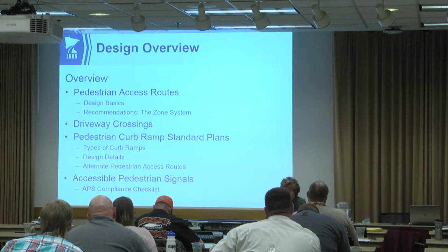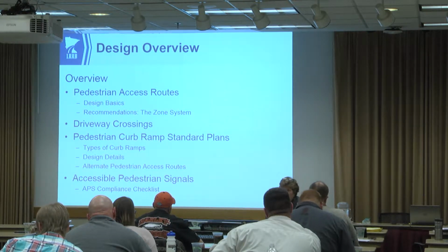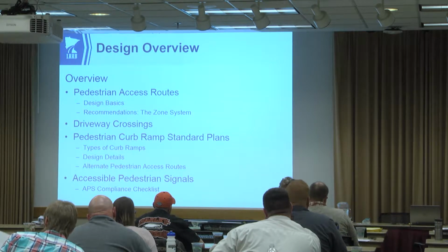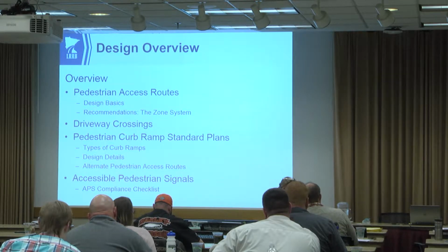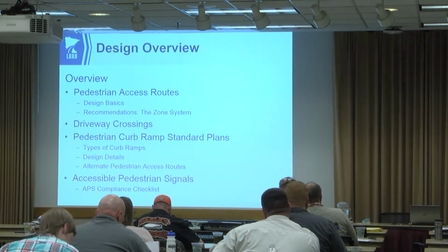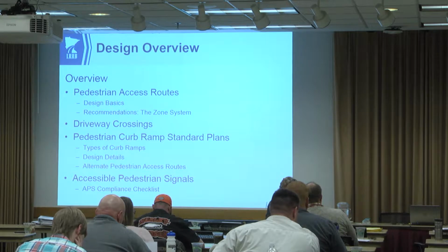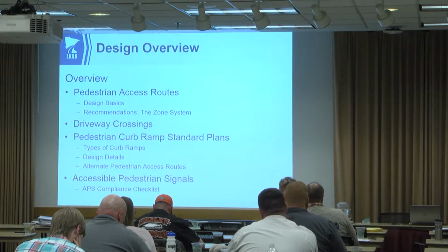I've been in construction a long time, and you know, we all nod and say, yep, we've seen a lot of plans that say contractor fit in field, grade to drain, whatever. And as an engineer out on a job inspecting, often for Met Council or others, that becomes very problematic because out in the field, you're trying to work with three-dimensional grading and drainage, and you got a contractor who wants to get it done. So unless you're extremely assertive and just say, let's just slow down a little bit, it's hard to do those things quality in the field.